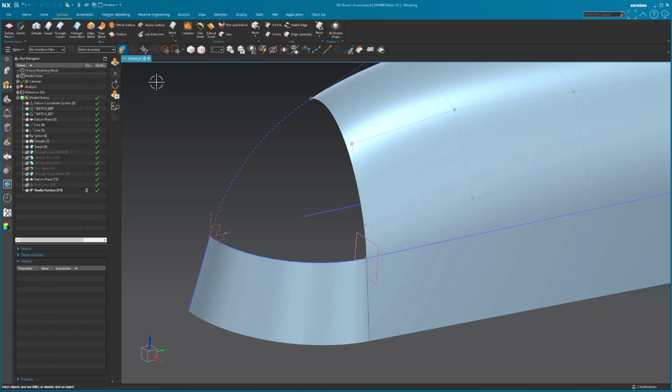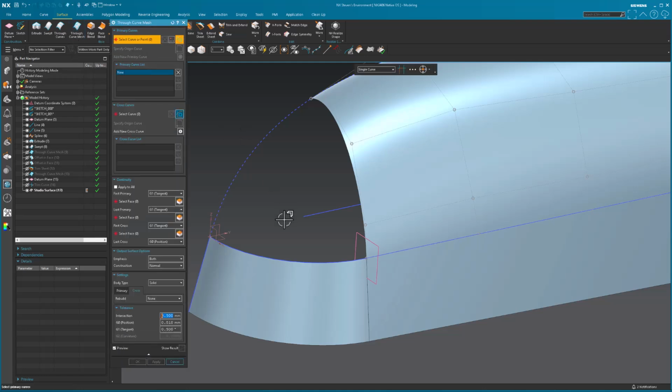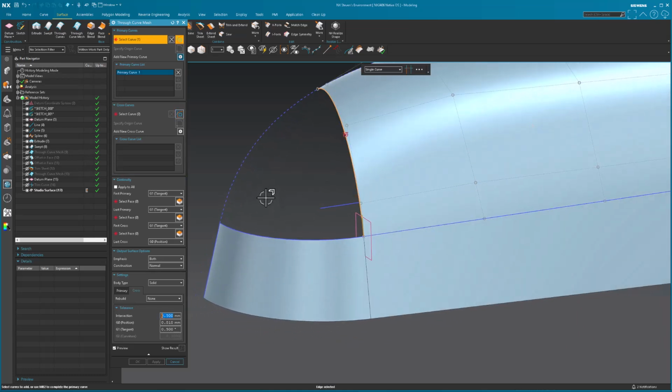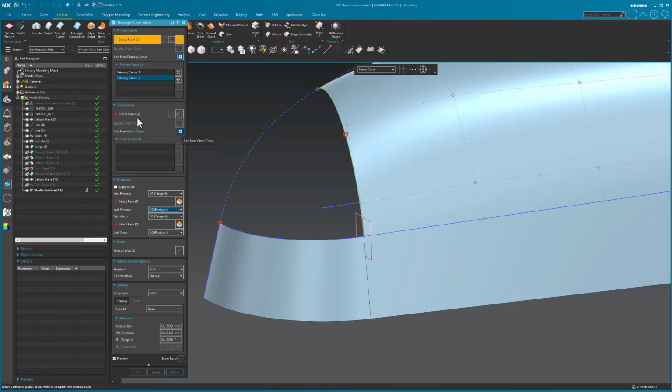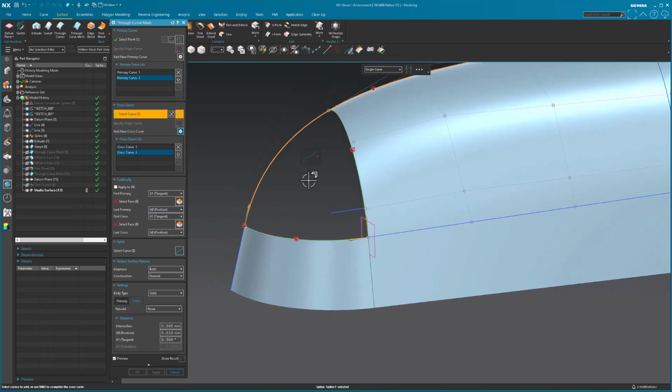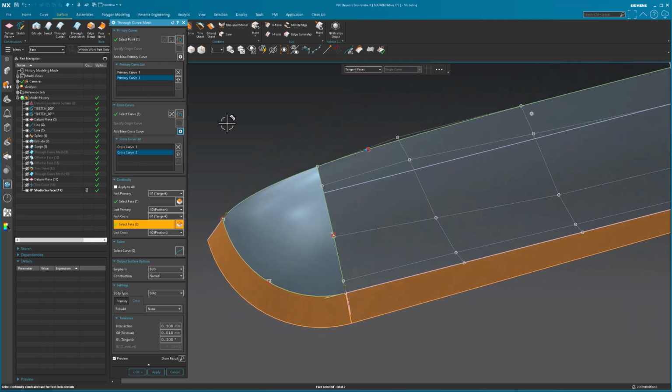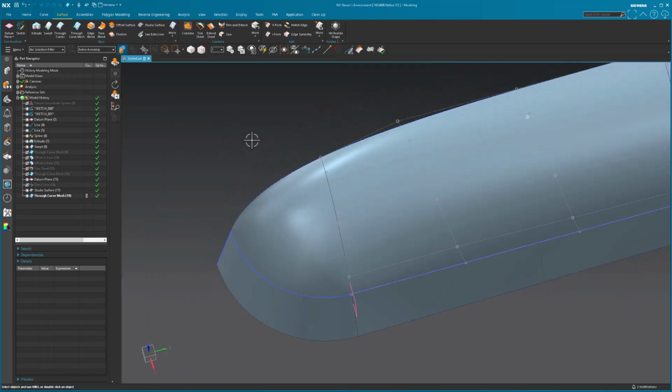Right? I can come in here and say, all right, I'm going to take, let me go ahead and hide this curve, tangent, go to this point, and it's just G0, there's no tangency there to be had. Cross strings, this guy, and another one, cross string, that guy. Okay, so now face number 1, first cross string, generate that surface. I'm going to select OK.